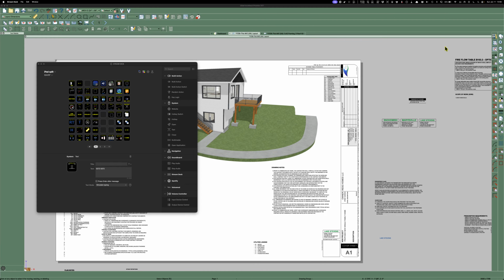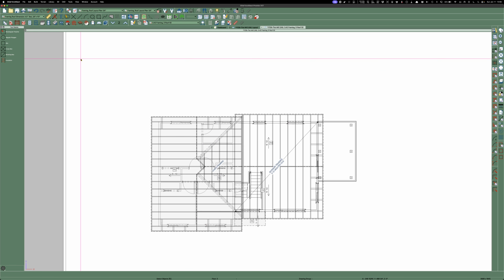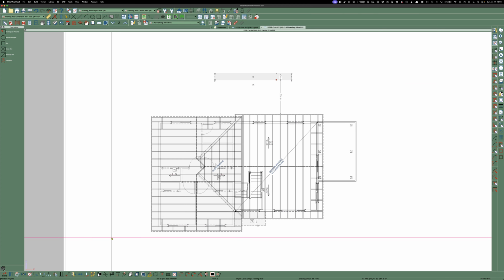One of the things that I noticed was when he wants to make parallel. Let me show you something kind of cool. So typically, if you had something and you wanted to make it parallel, if you just clicked on this and then you came down here and hit the parallel button, it's typically going to only parallel this edge, and the rest of this thing won't rotate.